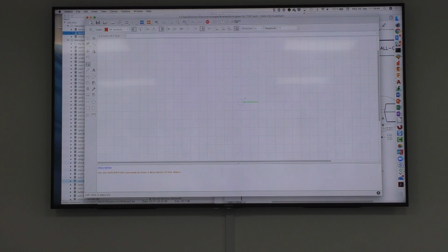This works in the way that I go into the schematic editor, click on the pin swap, click this net, that net, and the nets are changed. You can also use this in the layout editor. If you're routing 2 wires and you see you have a crossing, and if you're in the lucky situation, then you can swap pins, and you could do it so you avoid such crossings in the layout.